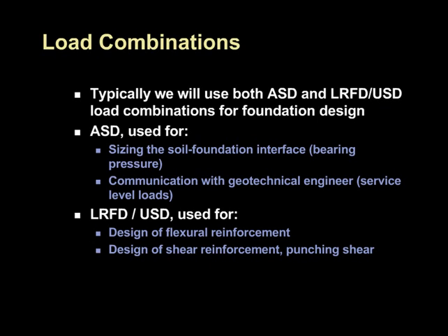I think everyone understands that when you enter the foundation design world, you need to use both allowable stress design and LRFD load combinations when you're designing a foundation element. At least in current practice, what would commonly be done is you would use allowable stress design, which I'll call ASD moving forward, for sizing the soil foundation interface for a spread footing. That might be just checking bearing pressure under a spread footing. Or if you're talking about a deep foundation element, it may be checking skin friction along the length of a deep foundation. You're also commonly going to use allowable stress design loads when you're talking to a geotechnical engineer.